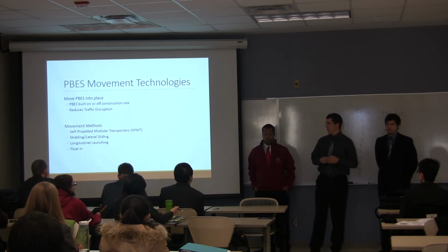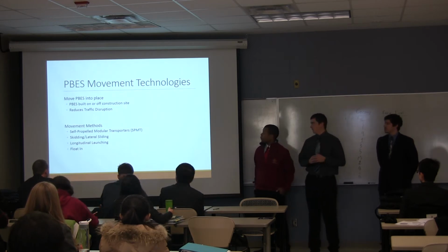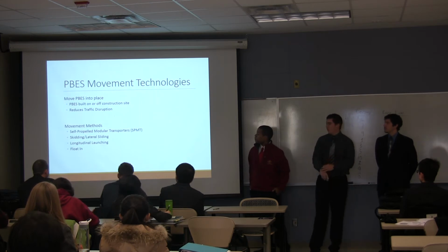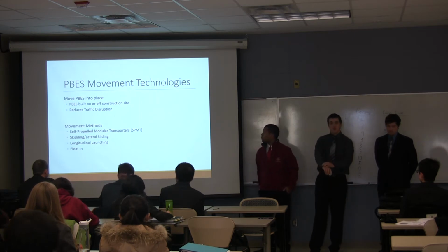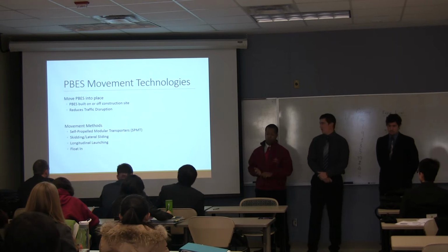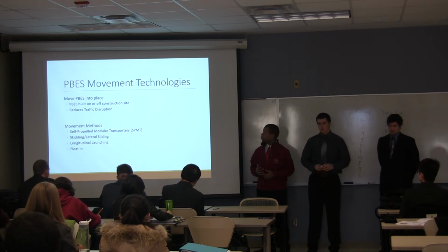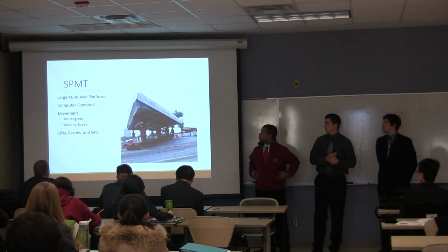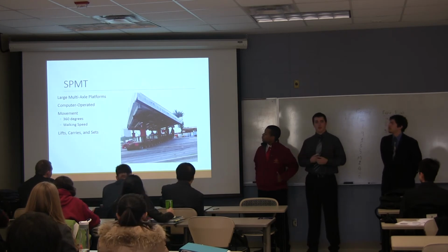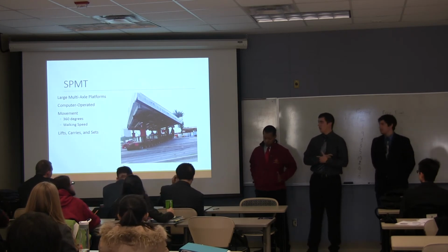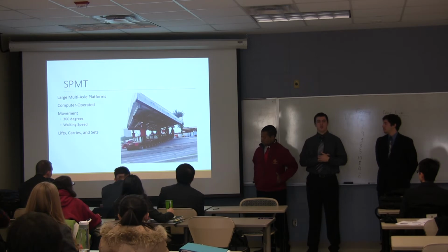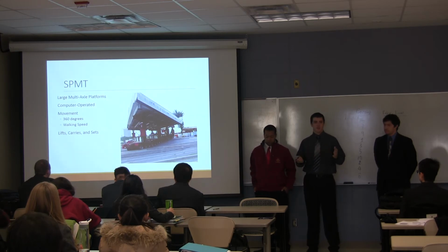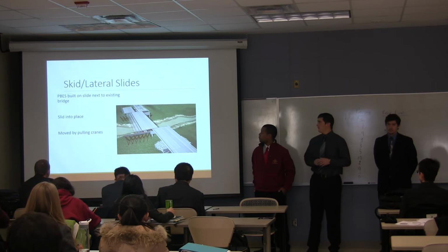One is the self-propelled modular transport, or SPMTs, skidding or lateral sliding, longitudinal launching, and float-ins. SPMTs are very large multi-axle platforms. They are computer-driven, can move up to 360 degrees, and move at a walking speed. They are used to lift, carry, and set the entire bridge structure.